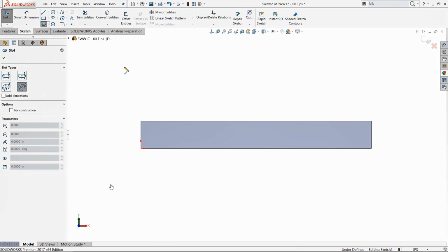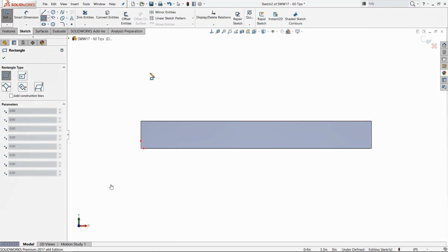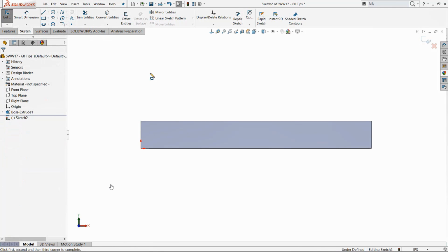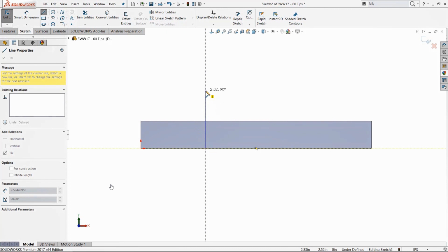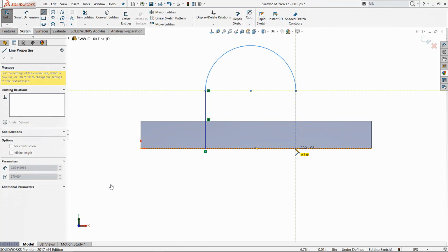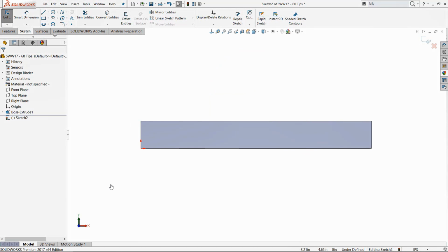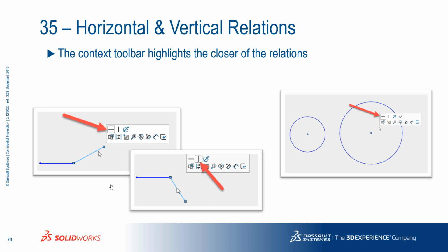All I'm showing you here is that the A key cycles through all those different commands, right? Rectangles, slots, there's a lot of different types of these entities that can be added, so hitting the A key just cycles through them, right? Now, I'm drawing a line, I hit the A key here, it turns into an arc. So that's a good way to auto-transition into an arc. And there's even slicker ways to do that, but the tip here is it's the A key to do that.